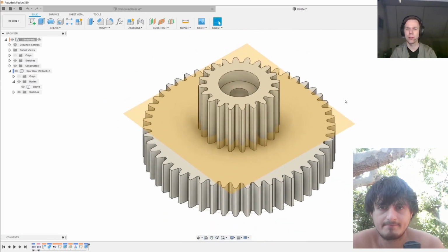The advantage to this technique is that you no longer need to create space for the bearings inside the housing of your gear train, and this allows you to make the housing a little bit more compact. The downside is that instead of the inner race, the outer race of the bearing is now rotating, and this causes the RPM limit of the bearing to be a little bit lower than the specifications would imply. However, usually I don't get anywhere near the RPM limit for a bearing anyway.